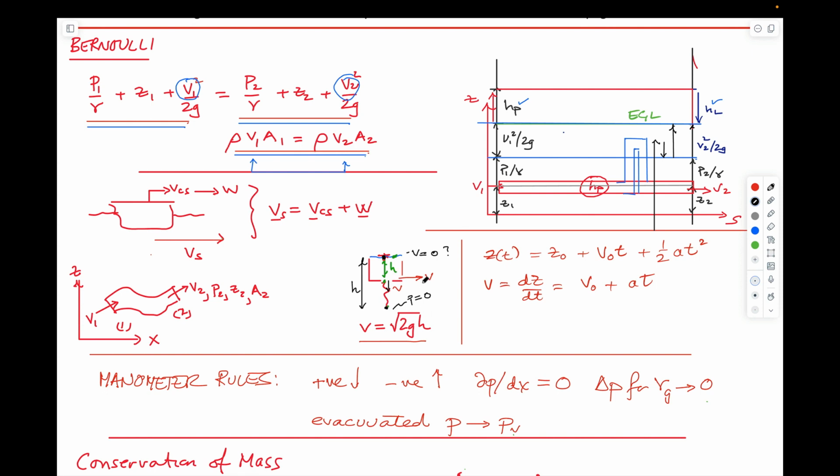If we have the free jets coming out, we know it's exactly the same behavior as if we were dropping a weight, and so it will tend to fall under gravity, as it does here. We did a simple calculation in class to show that indeed the convective acceleration at this point is equal to the acceleration due to gravity. But if we know those behaviors, that it will fall due to gravity at this point and it will keep on moving at velocity v exit horizontally, we can use those to calculate exactly the arc of this behavior.